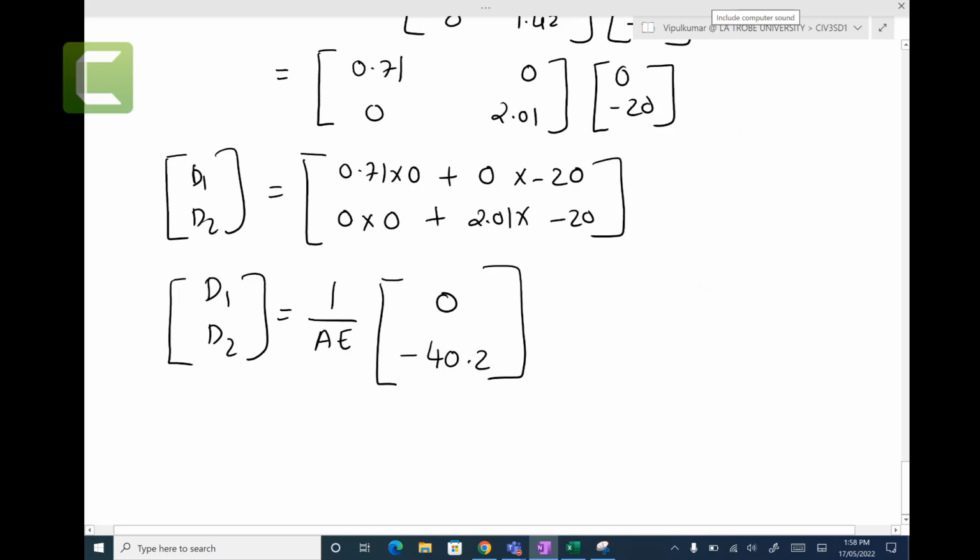ideal until the end. All right, so we're going to plug in the values of AE, and E is given in the form of E equal to 200 gigapascals. So we are working with length in meters and load in kilonewtons. Do you understand that, right? So far in the matrix, we are taking length in meters and load in kilonewtons. So we need this one in kilonewtons and meters. Do you agree with me?